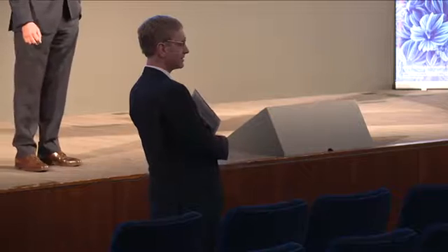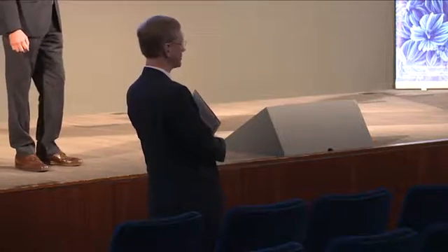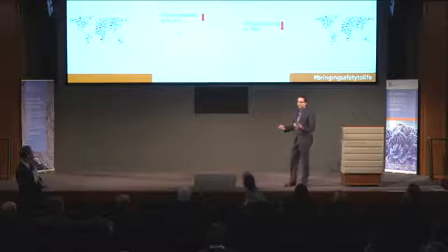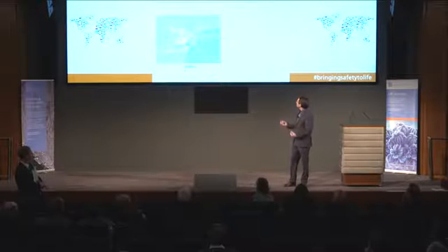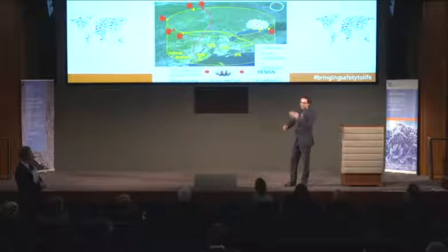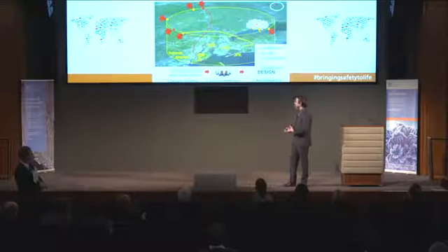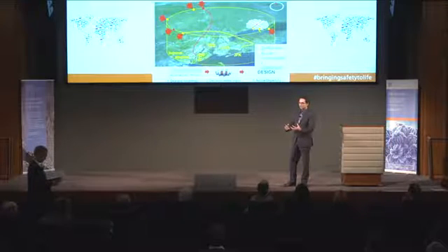I wanted to understand whether you took into account things like flight paths. I did. I actually designed the flight paths. So the third part of my model, where I talk about design of 3D arrival and departure routes, I actually designed them. It's an optimal design. As I said here, they are conflict-free. So you have different paths that there's no conflict between them. They account for aircraft maneuverability so that aircraft can actually fly them. And they are also optimal in terms of the total distance they travel within the terminal airspace. So it minimizes the total distance. So I take this design, I simulate it, and then I get these results. That's how I got it.